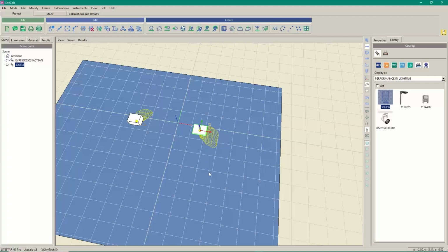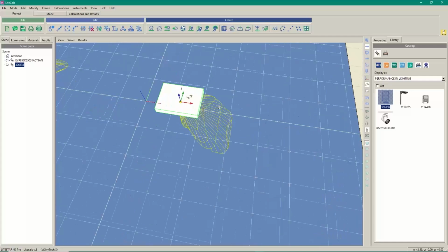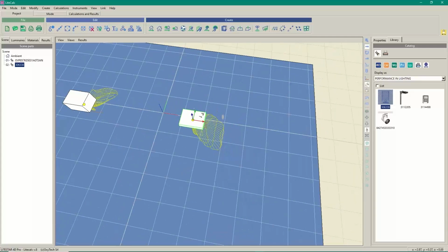So these are two asymmetric luminaires, but aiming is difficult. You have to approach the aiming of these two luminaires in a different way, because otherwise you won't aim one of them in the proper way. As you can see over here, the luminaire has a little red square, like the one over here, and this one is showing where the C half plane is directed.